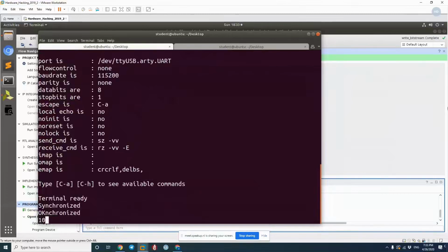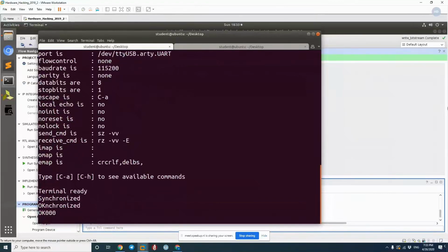So now I need to give it a frequency for the crystal. This is also just straight from the datasheet. We'll tell it 10,000. This doesn't really matter, but we need it as a command to actually initialize the bootloader. Okay, so it's happy. So now I can actually go ahead and send read and write commands. When it returns something, the responses will actually be UU encoded. So ignore that for now. It's not super important. It's just the encoding that NXP selected for this chip.